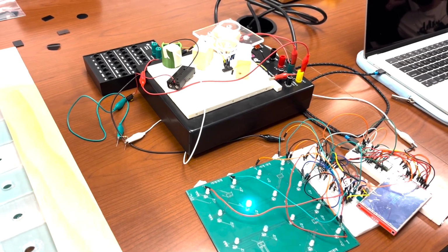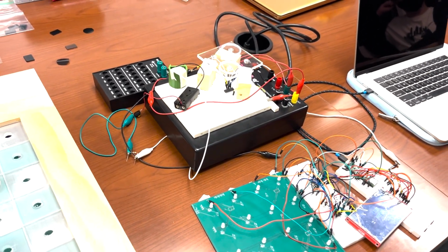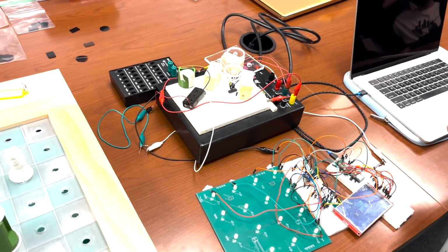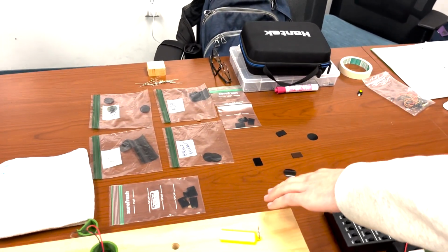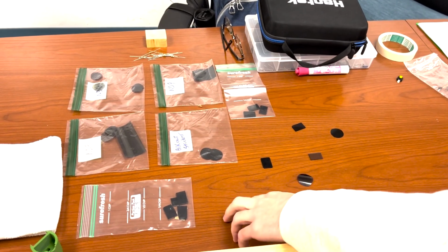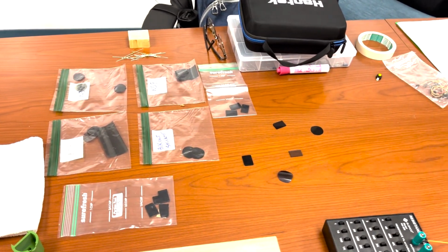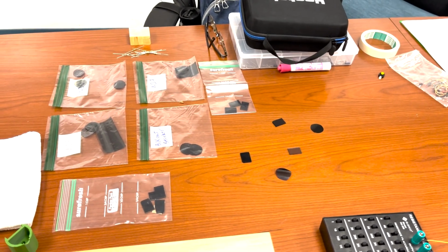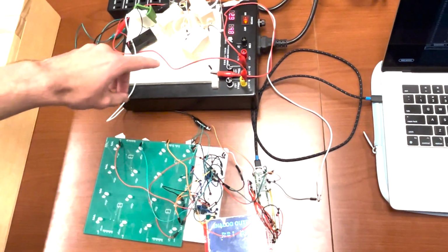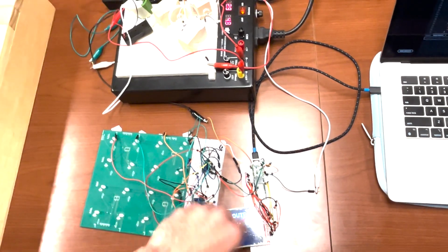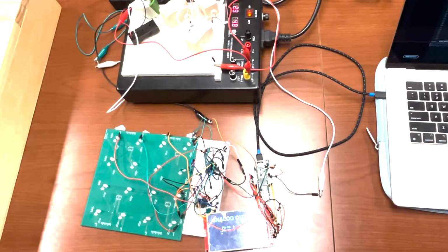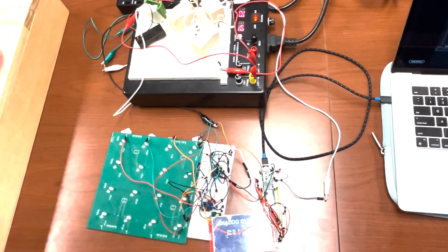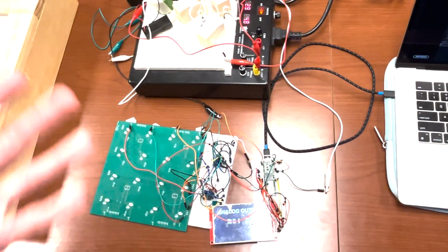3.3 volts. And then to differentiate the pieces, we're using various filters that will be attached to the bottom. We're planning on getting 7 different filters to differentiate each of the pieces in the project. As I receive the signal from the photodiode, it gets transferred along to the analog to digital converter on the Teensy. From there, that value is converted into specified ranges and into a certain value for identifying the piece.